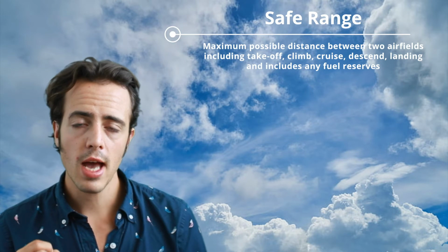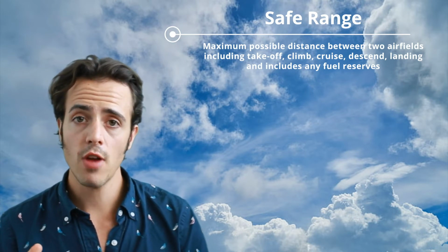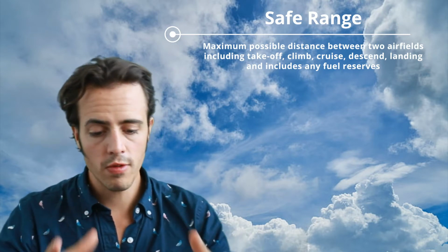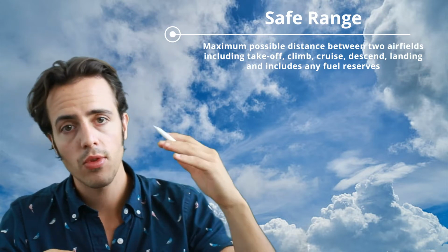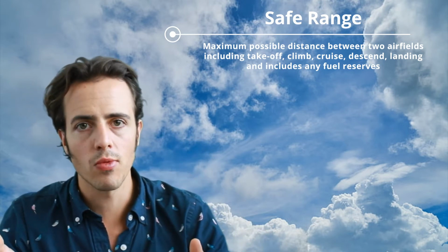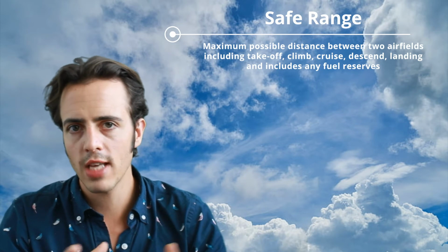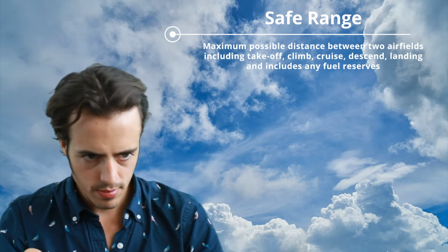So the first range, which is how far we can fly for, is the safe range. The safe range is defined as the maximum possible distance between two airfields that an aircraft can fly. Now this includes all of the calculations of takeoff, climb into cruise, and then landing with some fuel reserves as well. So it's a very detailed and involved calculation beyond what we're really covering in this course.